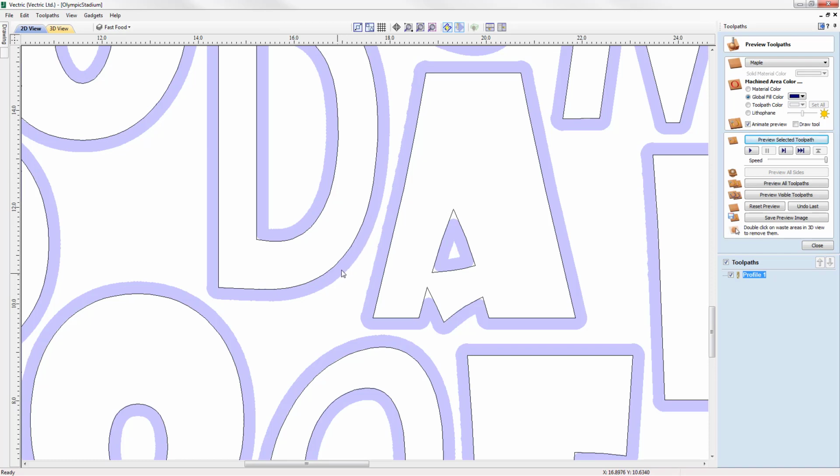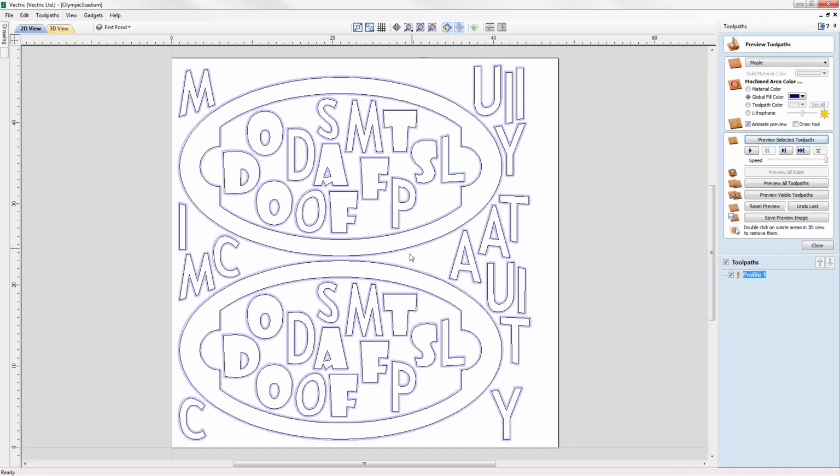We're doing a cutout here, and then here we have a minimum gap of 0.1 of an inch, which is that clearance that we specified, which could be used for tabs or just to keep it out of the way of affecting other finished areas, whereby in this example here we've got that 1/4 inch tool cutting the A out here. Okay, so let's have a look at another example of nesting.